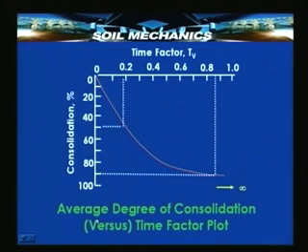Here is again the average degree of consolidation over the entire depth, and once again you find that at time factor 0.197 the average degree of consolidation is 50%, whereas 90% consolidation takes place at 0.848 time factor. Now, you will see that the point of 100% consolidation is rather difficult to locate.